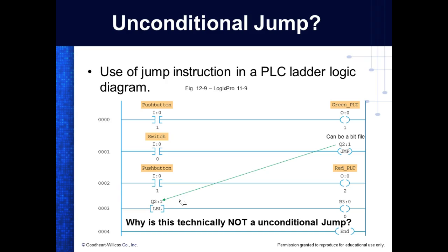You understand that? So this could be a sensor out there that senses a certain size thing coming through. If it's so big, it's going to send it this way. If it's not a certain size, it would send it another way. Well, I could use that situation to either send it down belt 3 or belt 4, depending on its height, or depending on its width or whatever we're doing. So in our program, we're using switches, push buttons, or selector switches. But you have to understand, these could also be a sensor that senses things and gives us a true or a false.